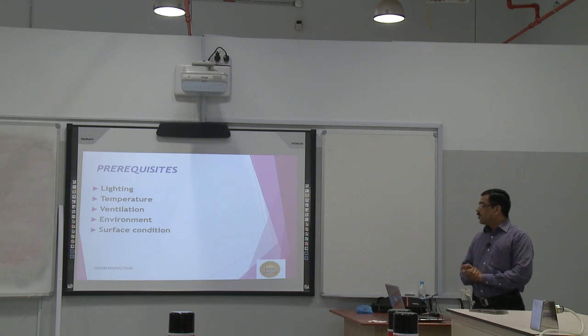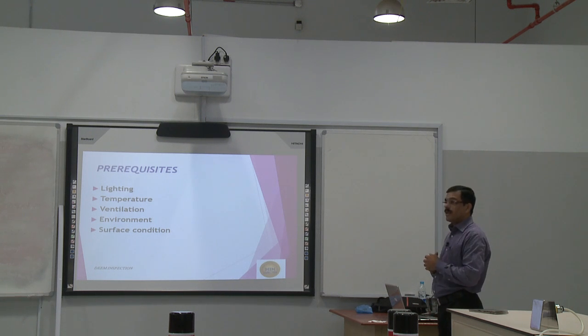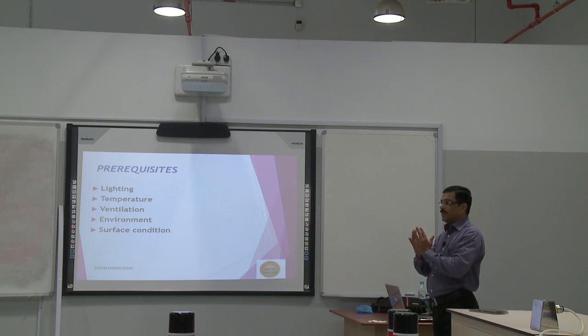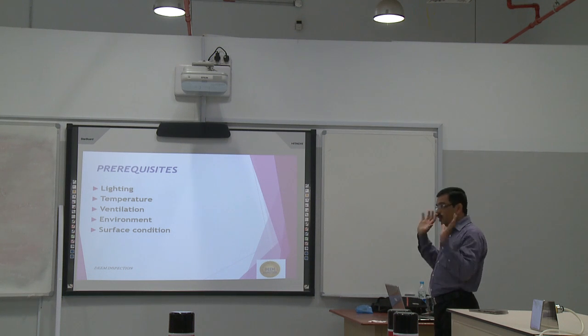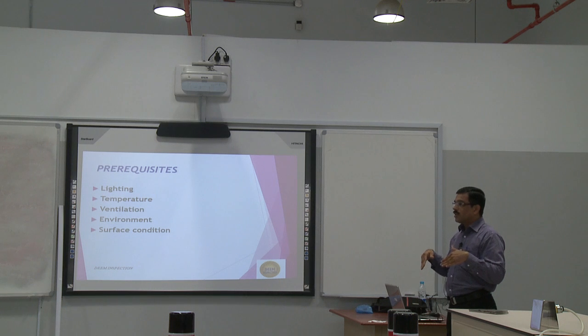And we have some more prerequisites. As yesterday with MPI, we need some lighting. Yesterday we talked about the lighting intensity, the white light. If it is in a closed area, we need a minimum of 100 foot candles. If it is outside, with no controlled light, we need 35 foot candles. Or in a closed area like this workshop, we need 100 foot candles to see the indication.